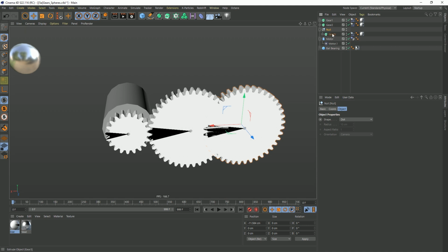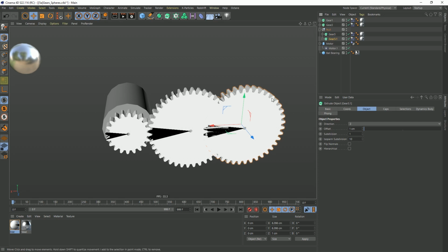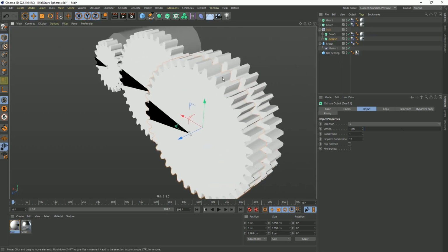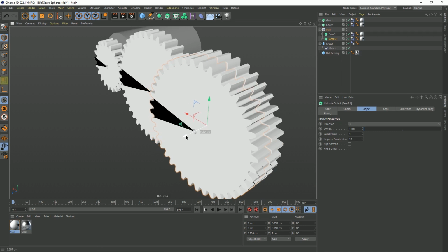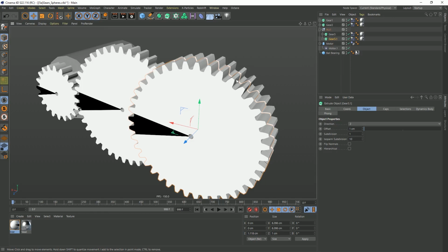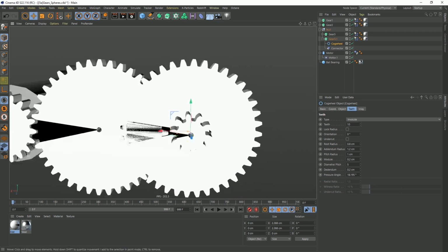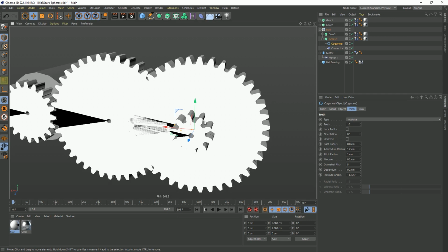I want 2 gears. So I'm going to duplicate Gear 3 a second time, scoot it forward. You do not have to be precise with this. Just make sure it's not intersecting. Actually, it doesn't even matter if it intersects, but I'm going to make sure that they're not quite touching. So there's 2 gears there now. The second one, the one in front, grabbing the cogwheel, I'm going to drop its teeth down to 10. Is it 10 I want? Maybe I want 20. No, we'll do 10. 10 should work. So this is now a 4-to-1 ratio.